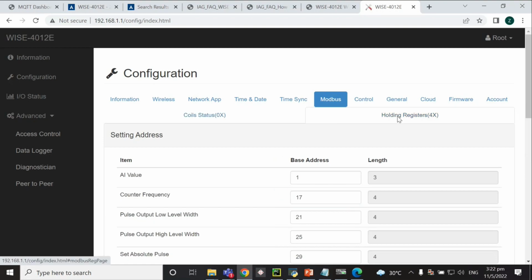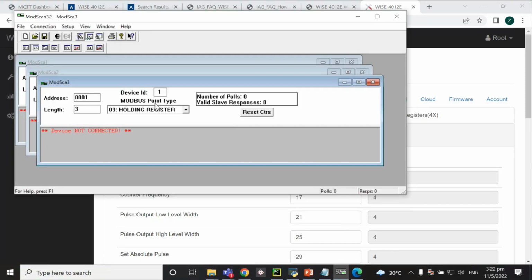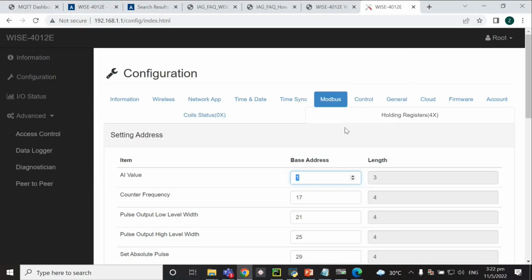Okay. Second one is for the analog input signal, right? For analog input signal, we have the type holding. I did mention to you, we only use two. For digital state, we only use the coil. For analog, we are using holding, right? That is the thing. So you will see from here our coil and holding.